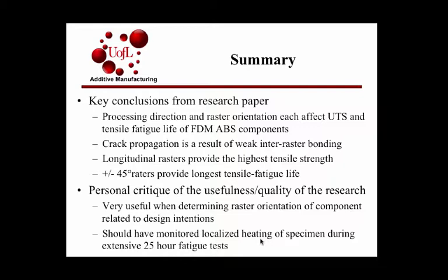My personal critique of this article is that the experiments seemed very well thought out, and all the analysis was very on point. One thing I noticed that they didn't talk about was if there was any heat generated during the fatigue test. If there was localized heating, maybe that would skew the fatigue results if there was heating in the areas where the parts yielded.